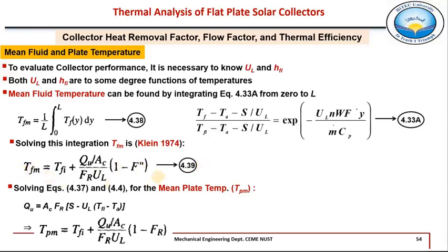Right, so the derivation of this equation 4.39 was not done, so now we shall do the complete derivation of this equation 4.39, and how this mean fluid temperature is actually calculated. It is based on this integration formula. So we have to integrate this fluid temperature in the y direction.